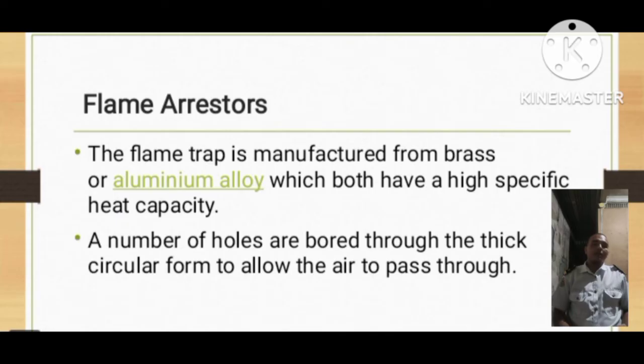Its whole intended function is to allow flow but prevent the transmission of flame in the event an ignition takes place. They are fitted in the main air line immediately before the air start valve to restrict the risk of a flame in the cylinder propagating back to the main air start manifold, by dissipating the heat energy in the flame.